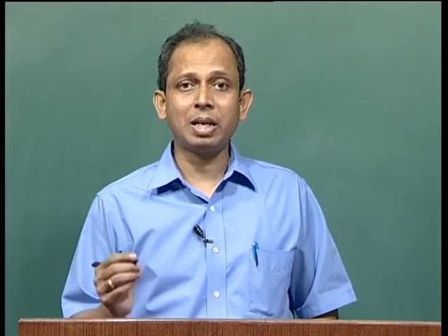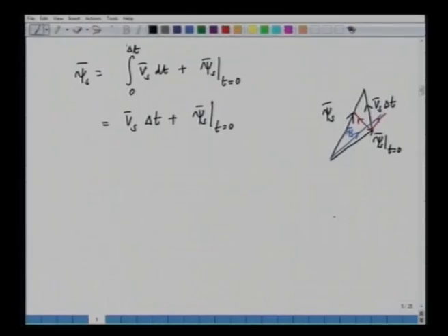The rotor flux in an induction machine lags behind the stator flux, because the stator flux creates the rotor flux. So, if we have the stator flux in this direction, the rotor flux is in this direction, psi r, and we are able to control the stator flux instantaneously by applying a suitable voltage vector.